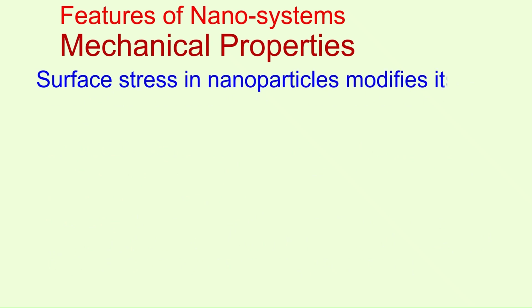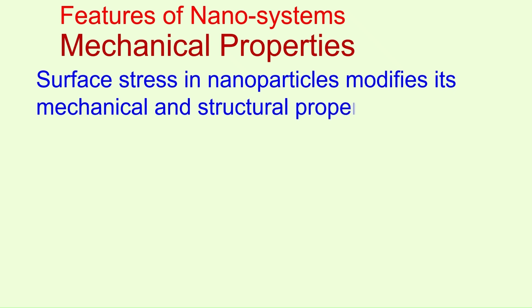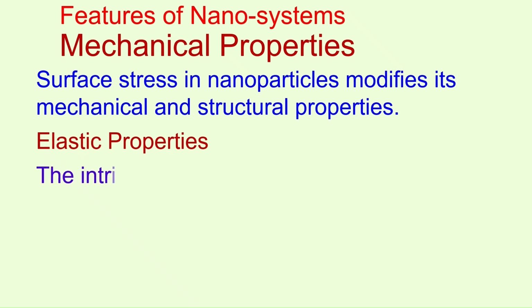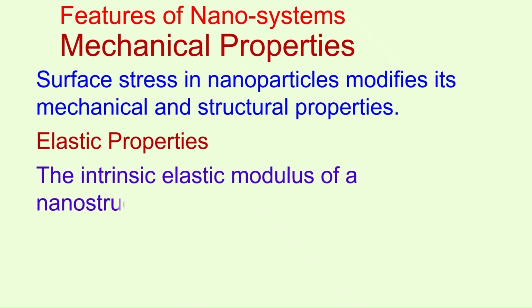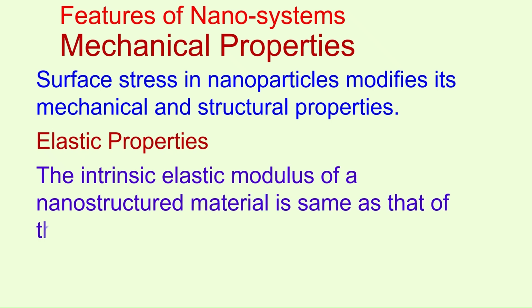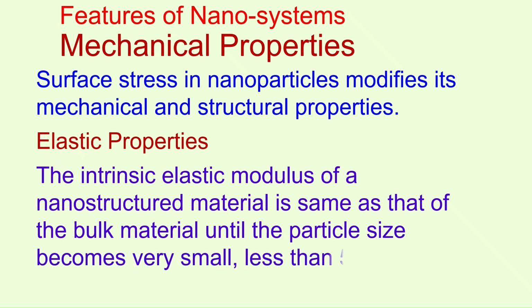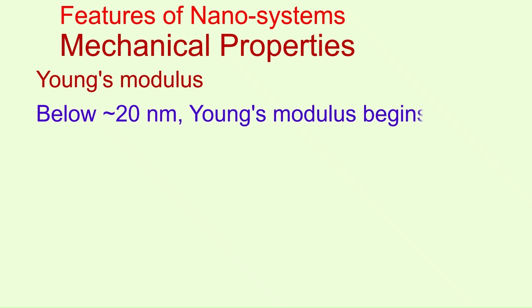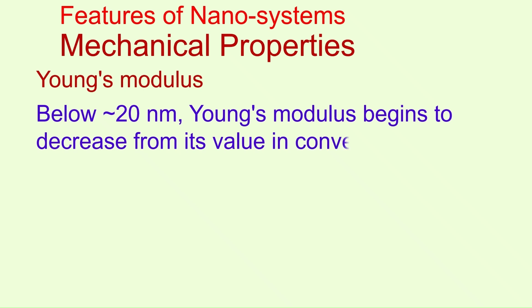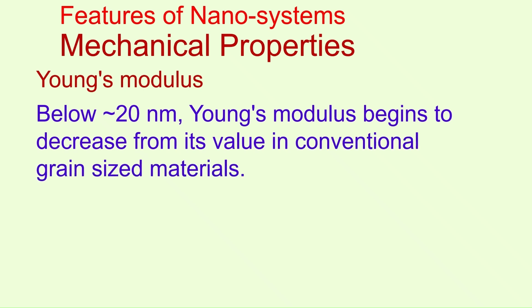Surface stress in nanoparticles modifies its mechanical and structural properties. Elastic properties. The intrinsic elastic modulus of a nanostructured material is same as that of the bulk material until the particle size becomes very small, less than 5 nanometer. Young's modulus. Below ~20 nanometer, Young's modulus begins to decrease from its value.